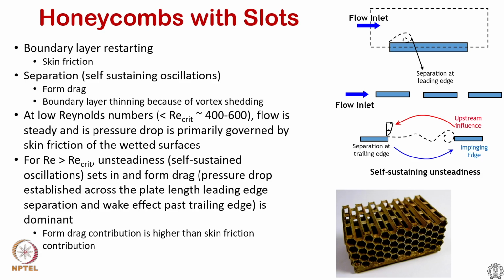Moving on, one of the reasons why these heat sinks had some issues is that a lot of surface area was added, and whenever you increase surface area, your pressure drop also increases, which is the skin friction coefficient. Also, within the heat sink itself, there may not be sufficient mixing, and the flow going through the bottom duct will see much hotter temperature because it is closer to the hotter wall, while the flow going through the top duct will see lower temperatures. So, one has to mix these two to get better performance. Introducing slots or doing something else like this may increase the performance.